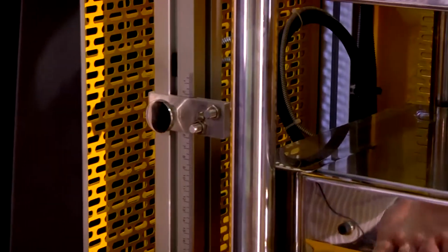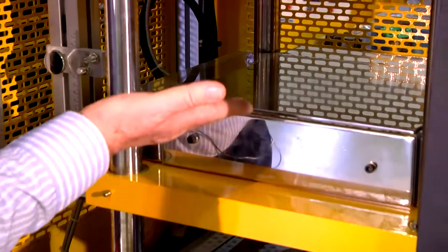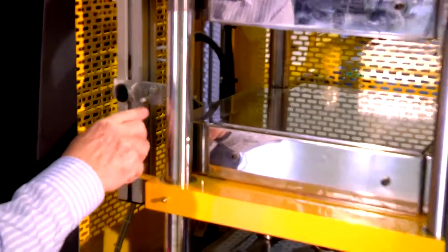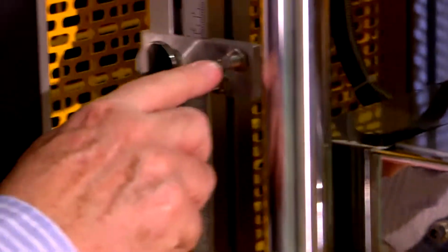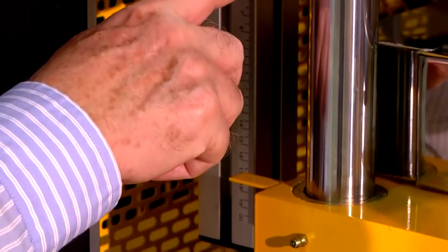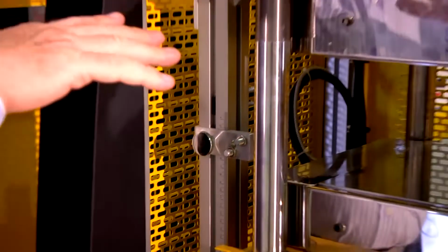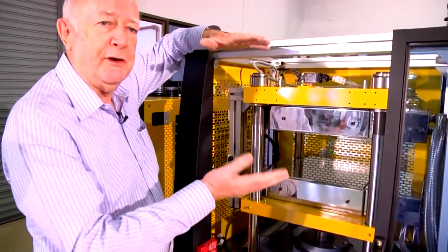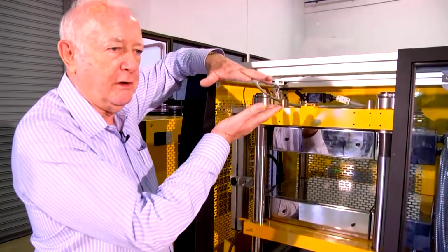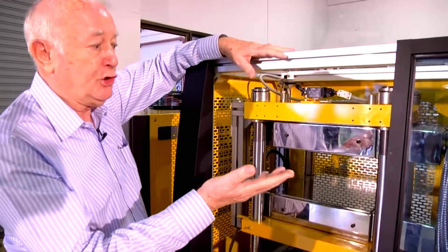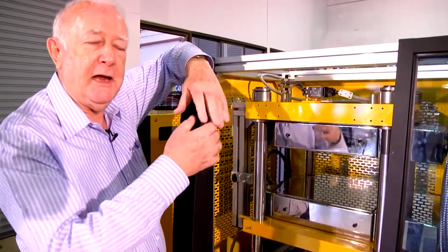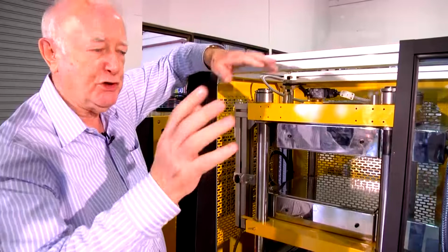So as the bottom platen rises, this little plate here will pass over here and over here, and one of these is for stopping the platens so that the pellets can be preheated. And then after that, the press would close under full molding pressure. And after a short time, the press will open for degassing to let out any gases like moisture.